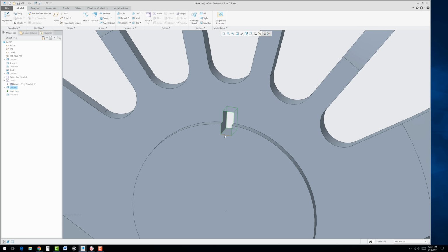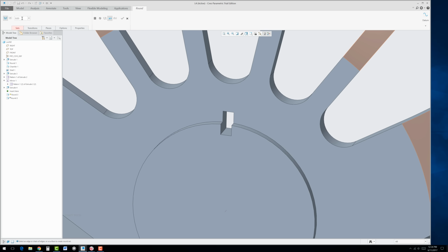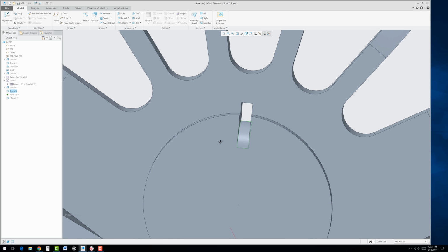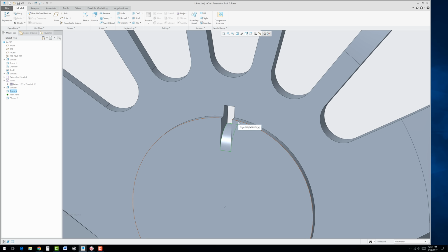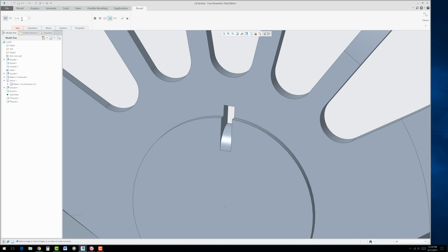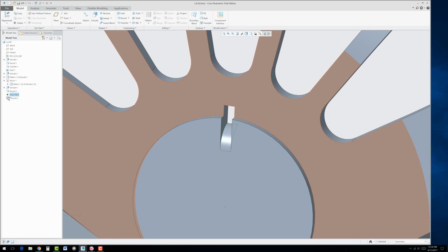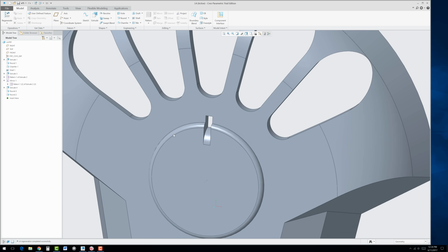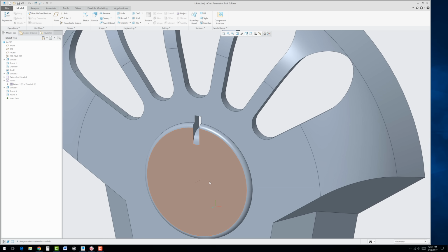Okay, there is a fillet that goes on this edge. We could go ahead and put that in there or put it in later. Sometimes with the patterns it seems to slow it down a little bit, but let's go ahead and put the round in. And the round needs to be 0.1. And we just select that edge there. It gives it kind of a little bit of character here. And before we pattern that, let's put one more round in here of 0.03. Oh, you know, I had that one in there already, so I could cancel that. And I could just drag this back down here, and the round is in position. And we still have a little axis we could use there.